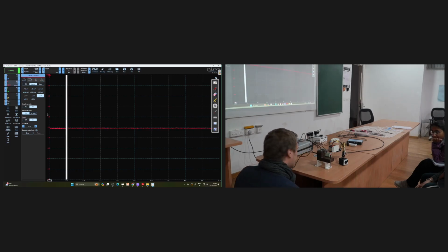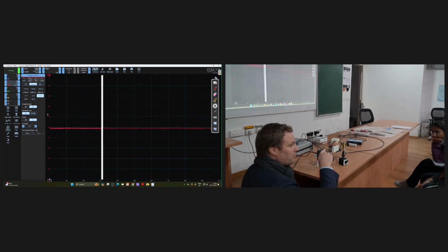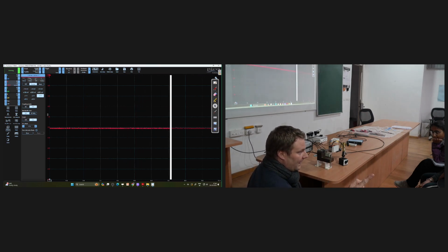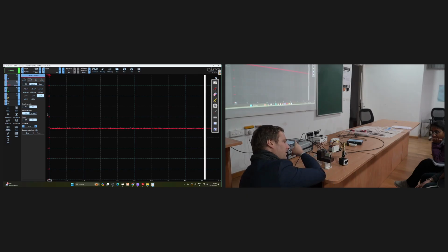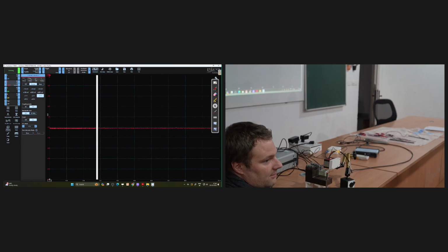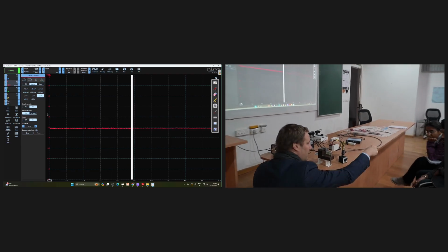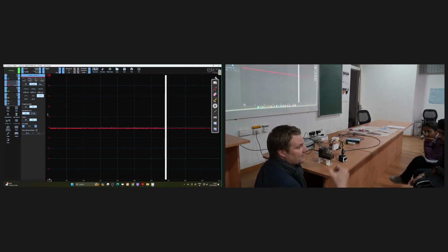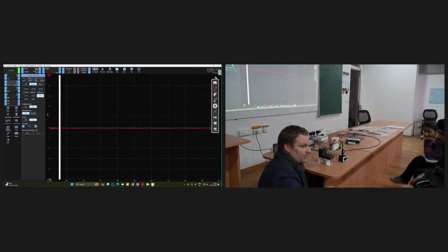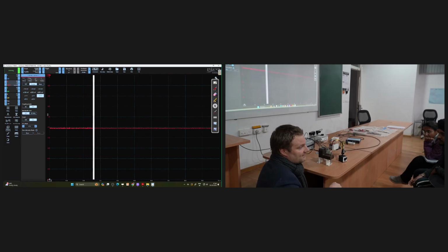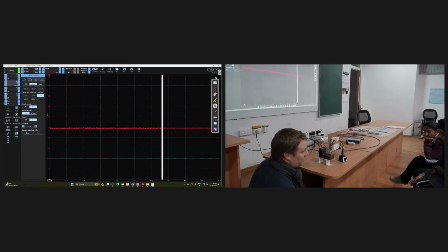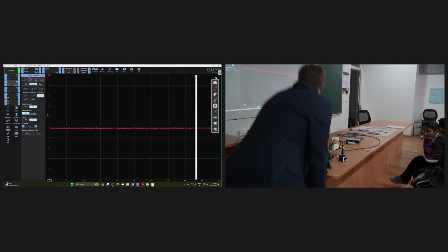So the next thing we do is a signal where we put first a high field on it, and then we do a negative field on it, and then a high field and a negative. So in the butterfly curve, or the butterfly diagram, we go from the left to the right, to the left to the right. And then what should happen ideally is that the elongation, which is the y-axis, does exactly that. You should see the butterfly curve in the end. So let's hope that works. It's always a thing with experiments.